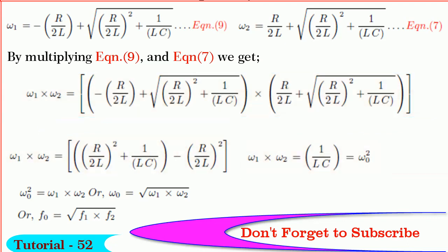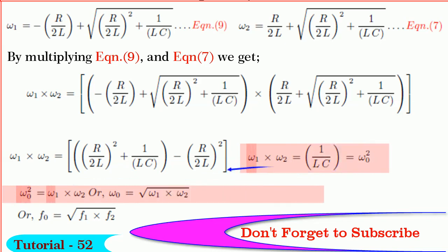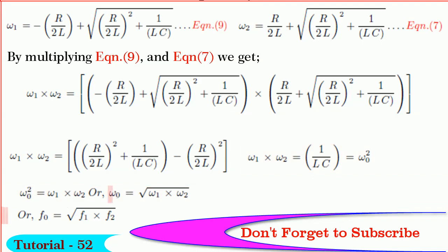But we know 1 divided by LC is equal to omega naught square. Therefore, omega naught square is equal to omega 1 into omega 2, or omega naught is equal to square root of omega 1 into omega 2, or f naught is equal to square root of f1 into f2. Hope you understood it.